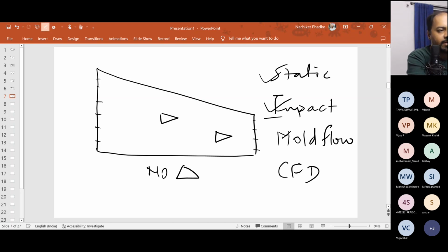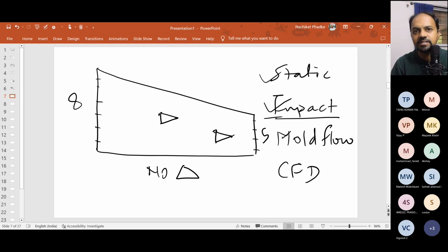So the number of elements here is, for example, 8. The number of elements here will be 6 or even 5. Now this will create these triangles because these two nodes get converted to one, and you will have a flow. Okay. And impact cases need this kind of flow. Element size is very important in case of impact or a crash.